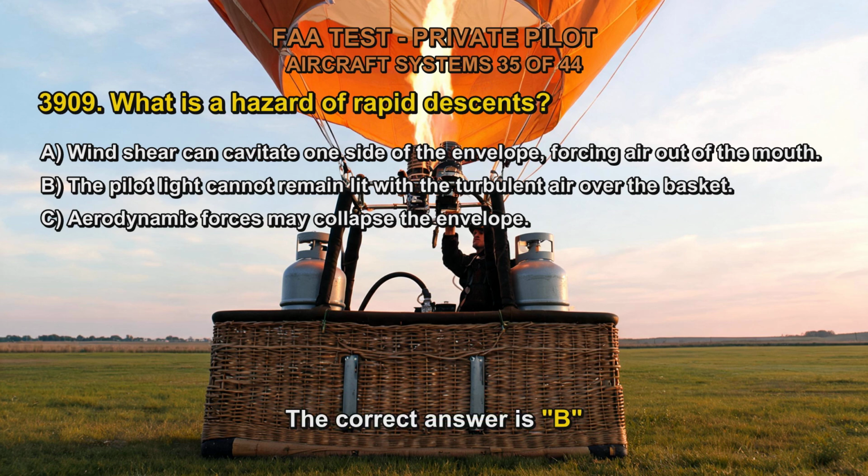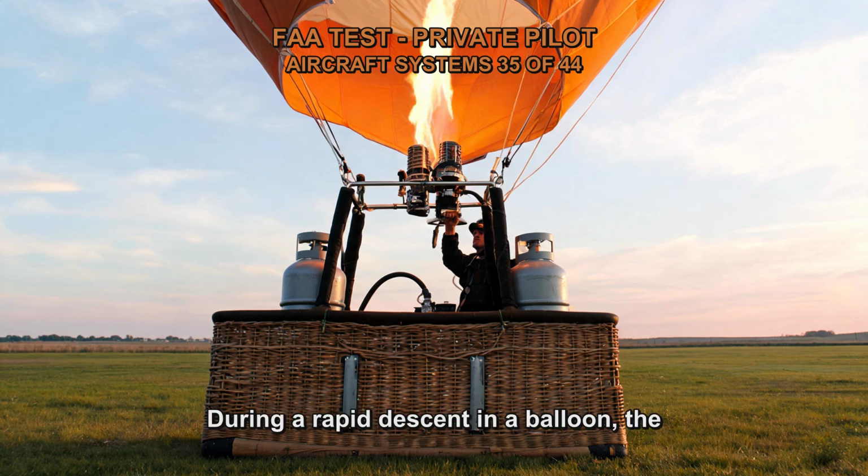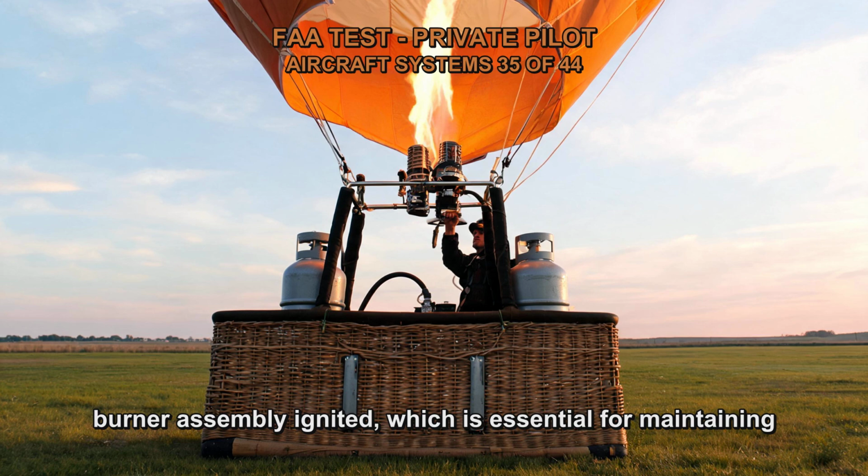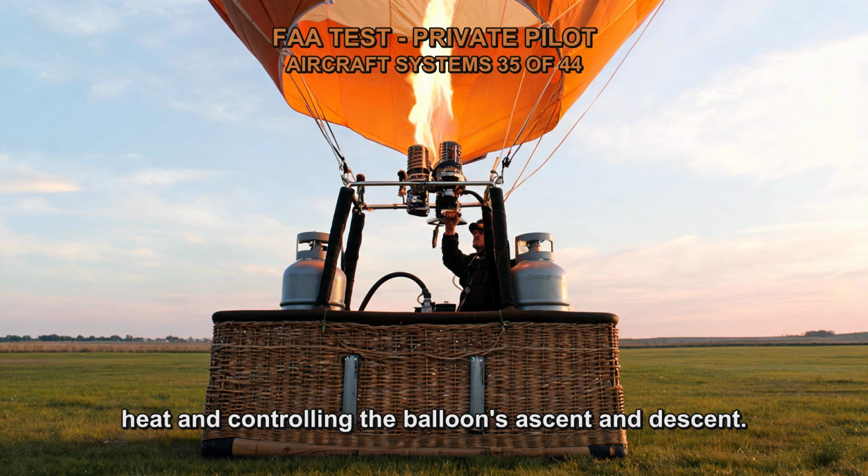The correct answer is B. During a rapid descent in a balloon, the turbulent airflow over the basket can disrupt the flame of the pilot light. The pilot light is responsible for keeping the burner assembly ignited, which is essential for maintaining heat and controlling the balloon's ascent and descent.